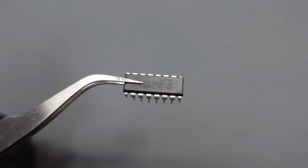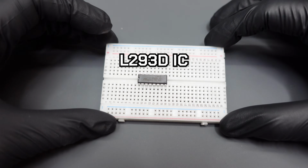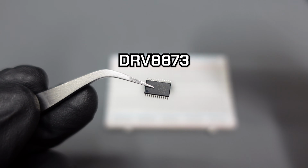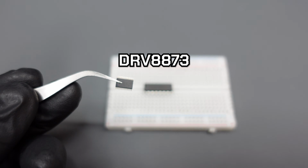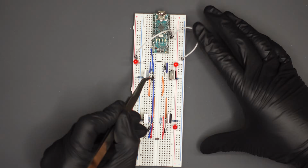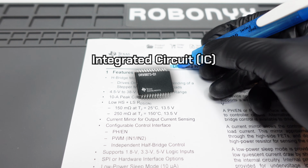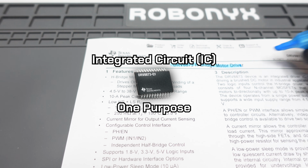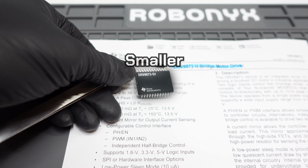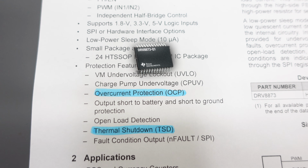There exist motor driver ICs like this L293D, which has a breadboard compatible package, or this DRV8873, which is even smaller and requires you to surface mount solder it to a circuit board to use it. Basically, someone took this whole circuit and put it on a single chip. And because it's an integrated circuit with one purpose, it's generally cheaper, smaller, more efficient, and comes with extra features like overcurrent protection and thermal shutdown.